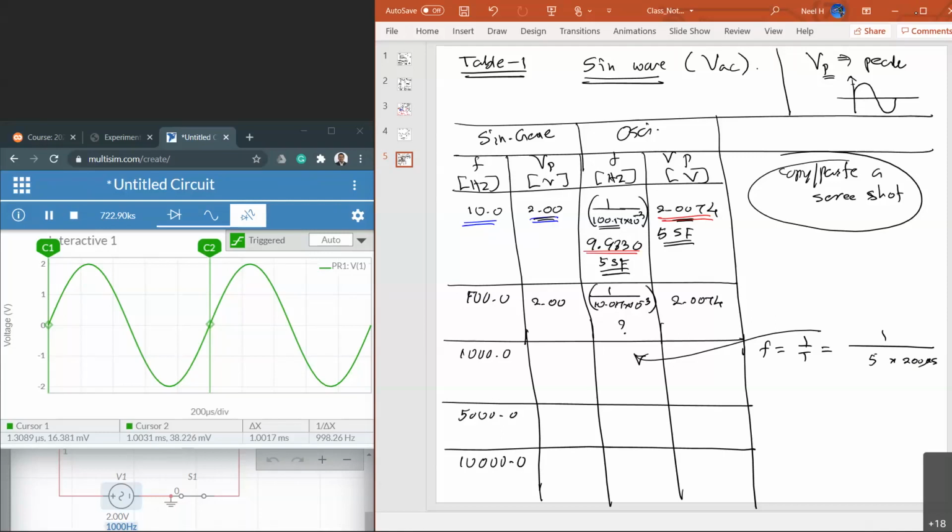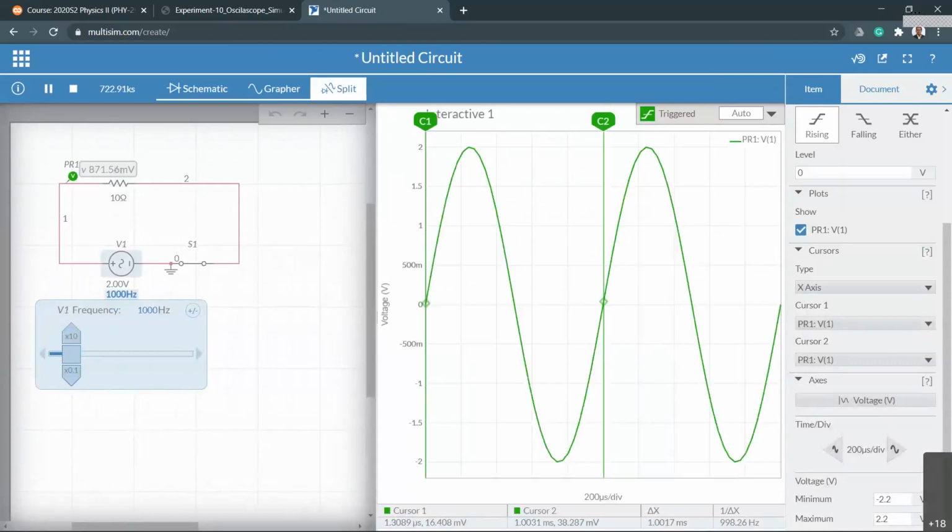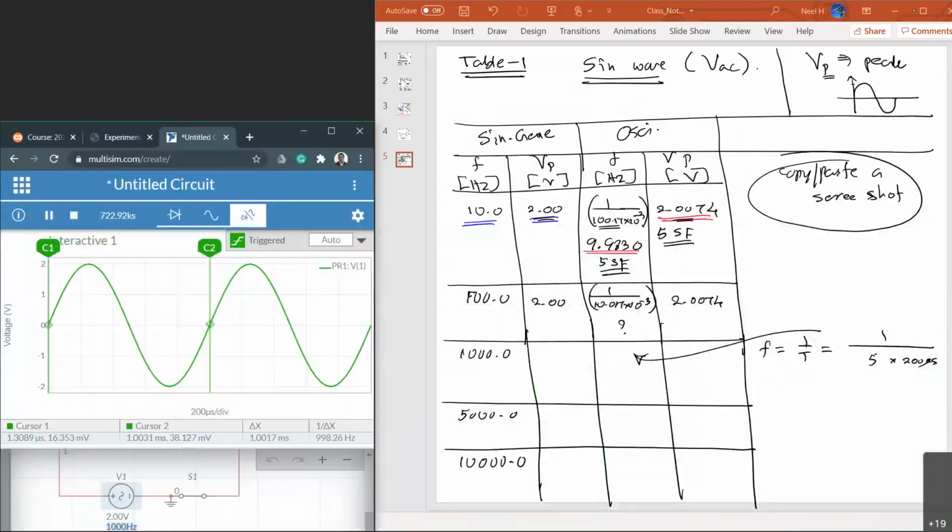Do it that way, then you actually have it right. Now it is updated properly, I think. Now it says 200 microsecond per division. Make sure you check that number right here and the number in your selection tool, the operation panel, because sometimes this x-axis unit does not update properly, and then you have a problem. If those two are updated, then you will get the right number.